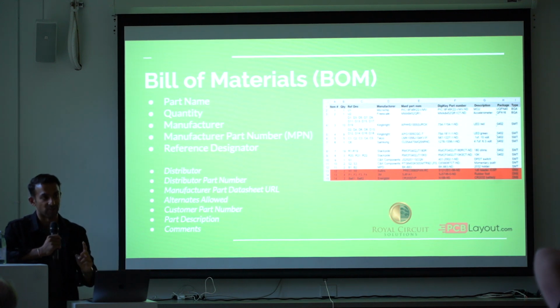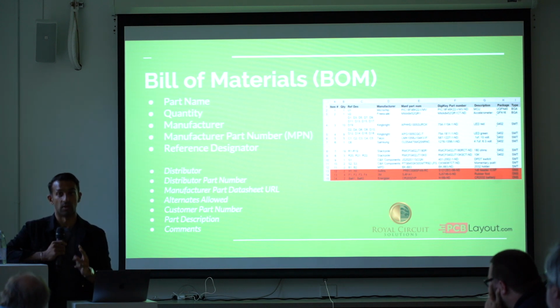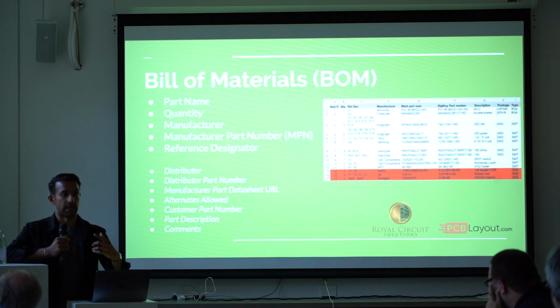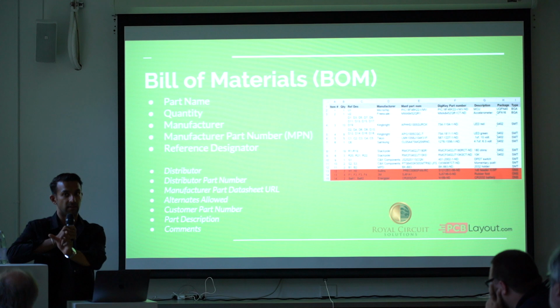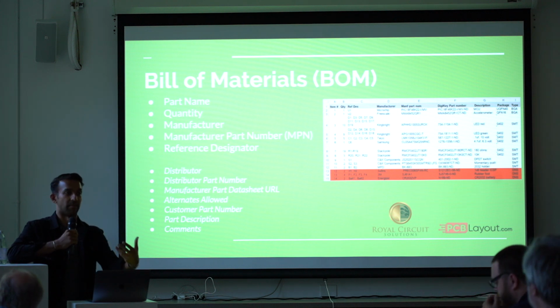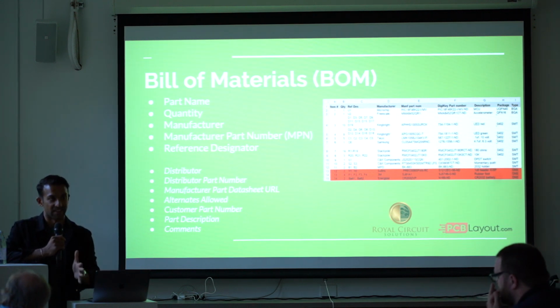But the one stat that has remained true is that 98% of jobs that come in have some sort of issue with the bill of materials, with a Gerber, with the footprints, or something not lining up. And usually it may not even be the engineer's fault. The Gerber has a 0402 package, but the bill of materials part says it's a 0603, but then you wrote in 0805. Which one is correct? We can't assume that the one we ordered, the part, the order link, and the fab, maybe one of the smaller parts, I don't know. And oftentimes there's not a clear note, and we're running these so fast. If it's not explicitly clear, it's a huge issue.